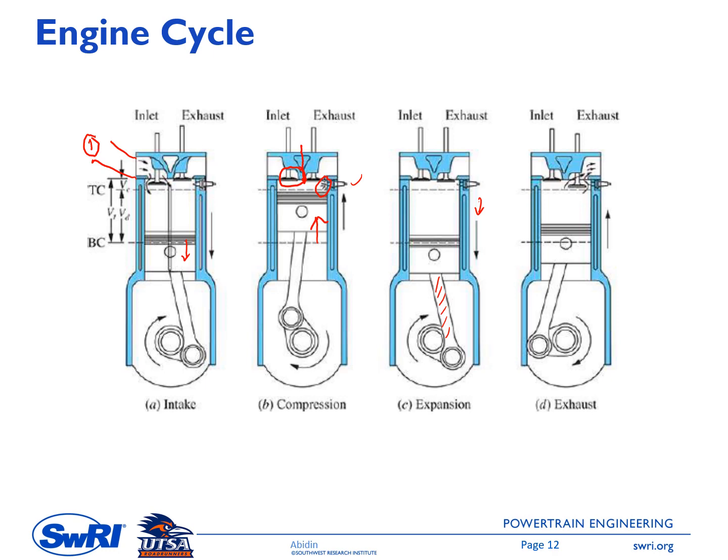wheel, or it will propel the dynamometer wheel. During this expansion stroke you can see in here that both valves are still closed, and the piston moves down toward bottom center, and then at some point before the piston hits the bottom center the exhaust valve opens. We'll have more explanation about this later.